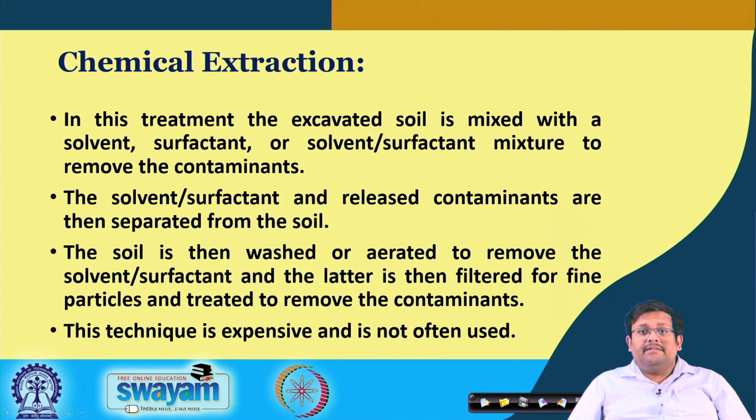The next method for ex situ soil treatment is chemical extraction. Now, in this treatment, the excavated soil is mixed with a solvent, surfactant or solvent-surfactant mixture to remove the contaminants, and the solvent or surfactant and released contaminants are then separated from the soil, and the soil is then washed or aerated to remove the solvent and surfactant, and the liquid is then filtered for particles and treated to remove the contaminants.